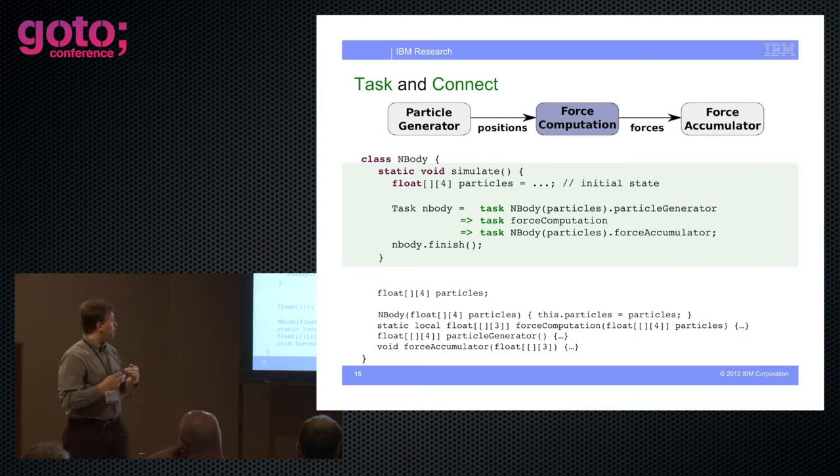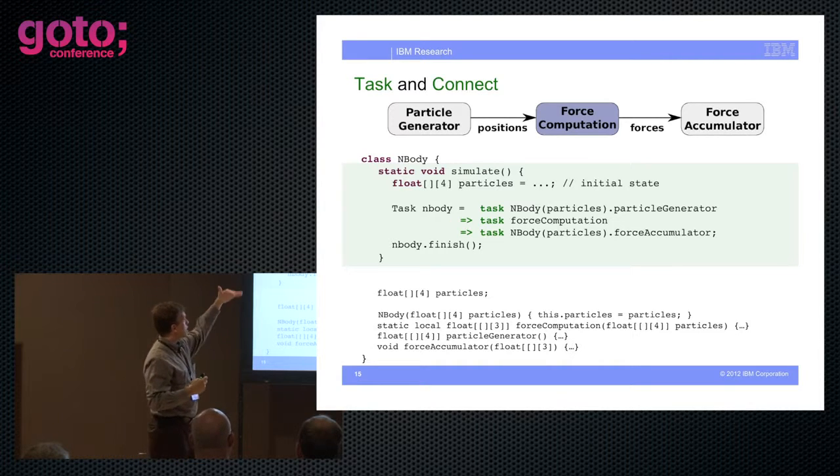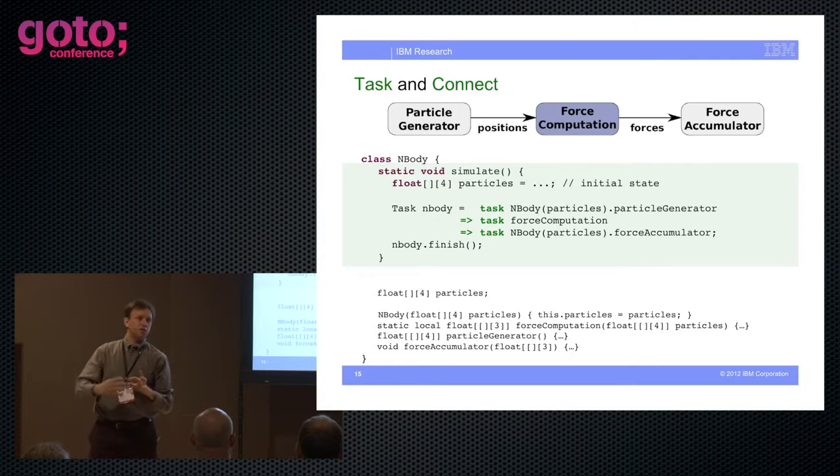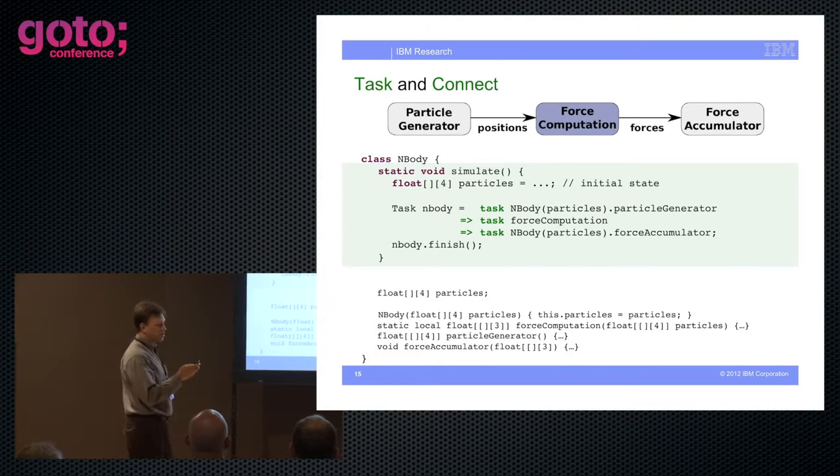So very often for hardware, what you'll do is set up a fairly rich task graph, which maps down to hardware, and this is the kind of thing that runs well in hardware, because each task, if it's in a pipeline like this, corresponds to a pipeline cycle in a pipeline design. And so it's very much in the style of how people do hardware design. I hope that's clear. I'll go through a few more slides and then clarify anything that needs to be clarified.